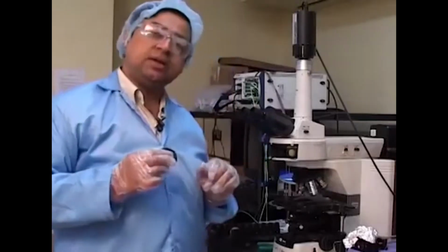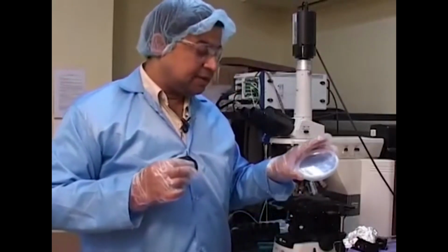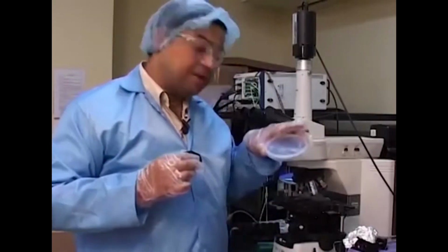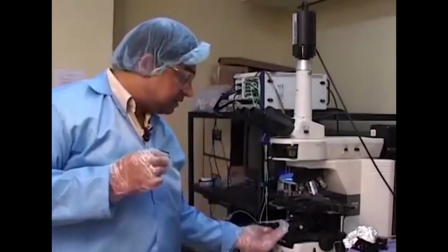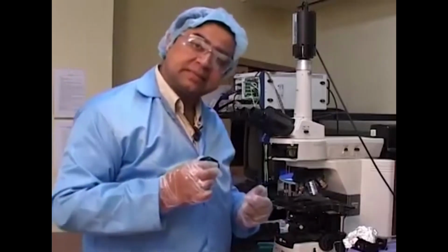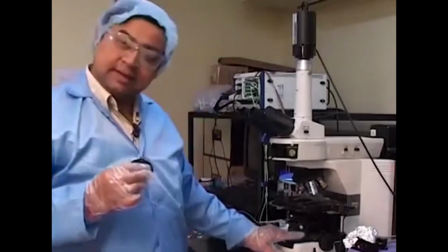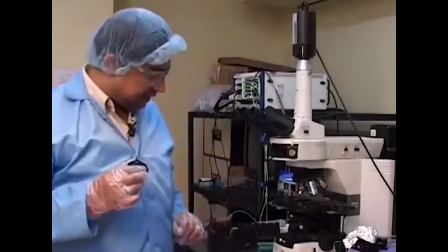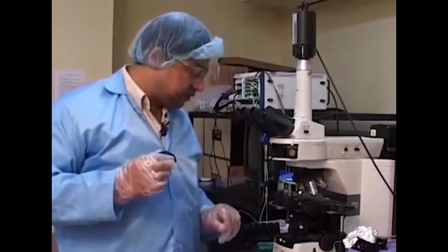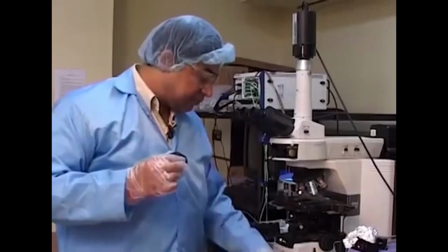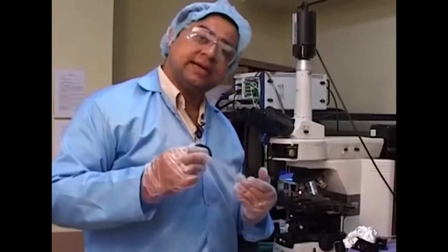Now, in a bright field dark field option, particularly for lithography, the problem that we face is that we cannot image these silicon wafers, which are actually opaque, using an inverted mechanism of light. In glass samples, glass holders, or transparent or translucent samples, that is still possible. There is a light source here in the microscope, which is actually white light, as you can see, which can go past the sample surface if the sample is kept at this particular stage. However, in our case, if I put the silicon and the silicon is opaque, the light will not be able to go past. So, this is really not the imaging modality we are looking at.